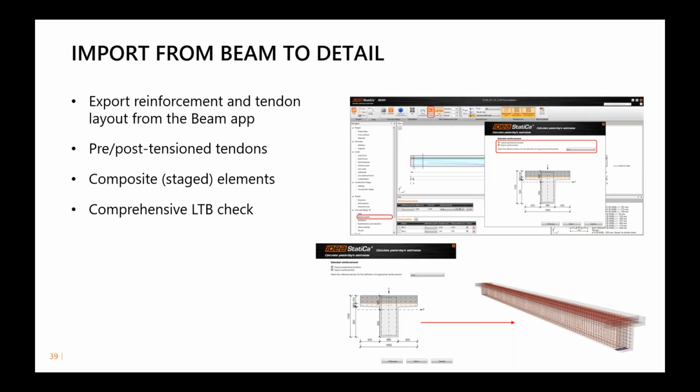So what is new in IDEA StatiCa Beam? The biggest advantage of this application is that it has time-dependent analysis fully implemented, so all rheological effects such as creep and shrinkage are automatically considered. That means this application is perfect for different types of staged structures, so let's say concrete to concrete structures. And usually such structures are either pre-tensioned or post-tensioned, right?